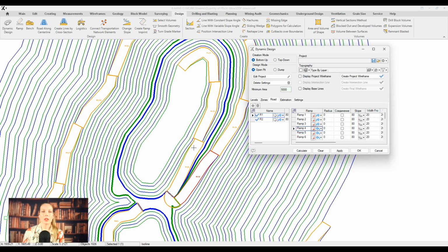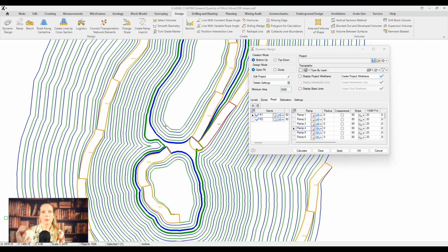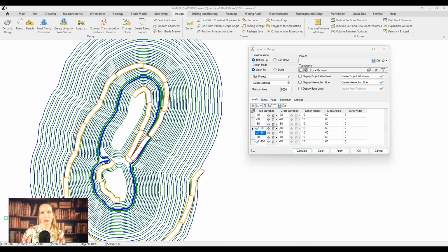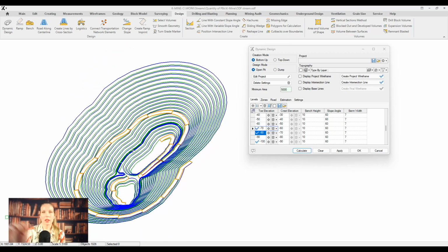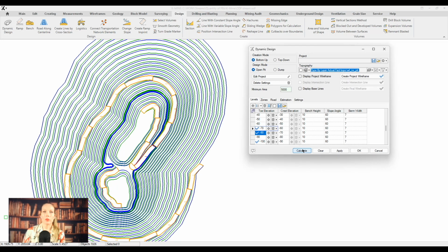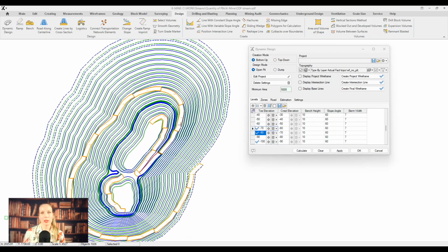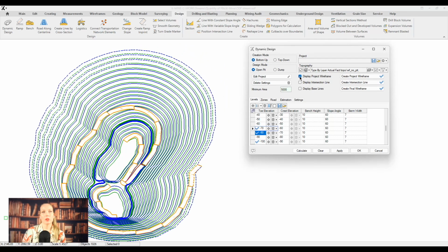This must be ensured at the design stage of the final pit contour, and all approaching roads must be interconnected to ensure flexibility in the transportation of materials. Then we introduce the topography into the project and recalculate. This shows us which lines are above the ground level, which is crucial because our project must intersect with the topography to work correctly. The plugin has various visualization tools to make this process as clear as possible.